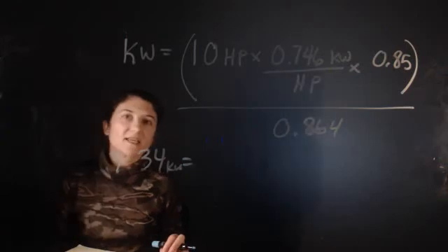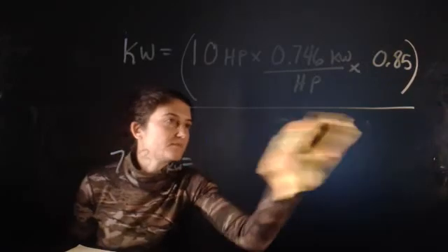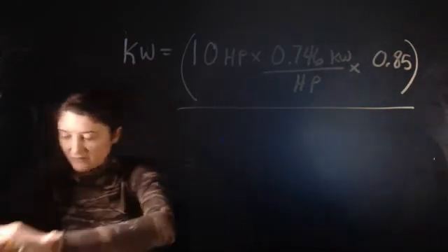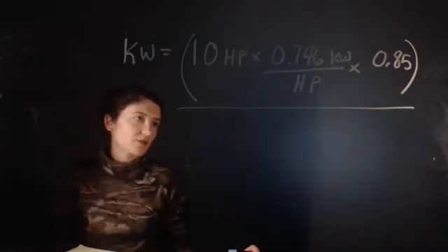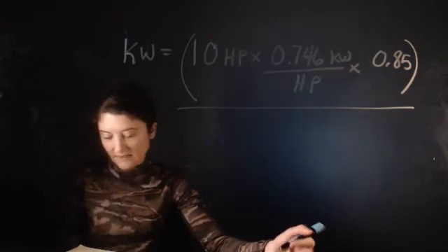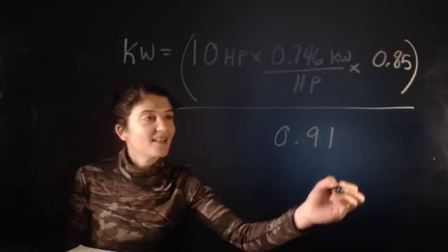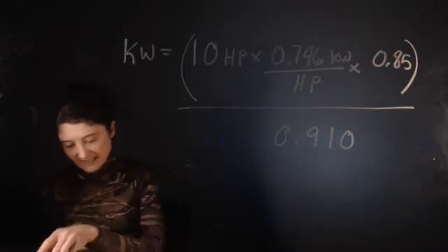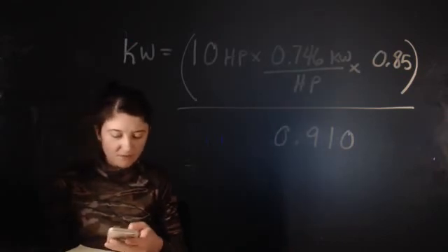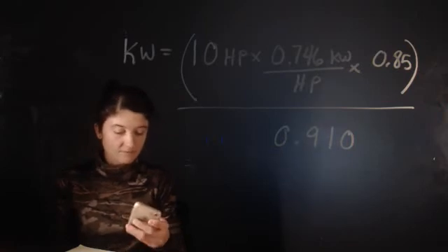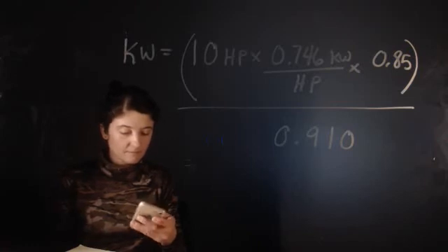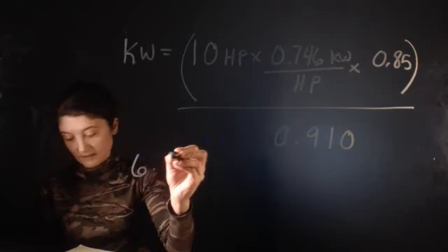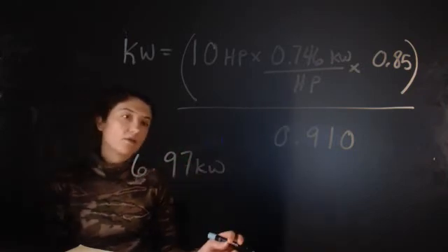Now let's say we replace that motor. And when you go to replace it, because federal law requires it, you must buy a NEMA premium efficiency motor. Federal law requires that we only manufacture and sell NEMA premium efficiency motors now. So you found a motor for the sledding hill that is 91% efficient, so a bump up from the standard efficiency. Well, if you recalculate how much power the motor would use at this new efficiency, you'll end up at 6.97 kW for the upgrade of motor.